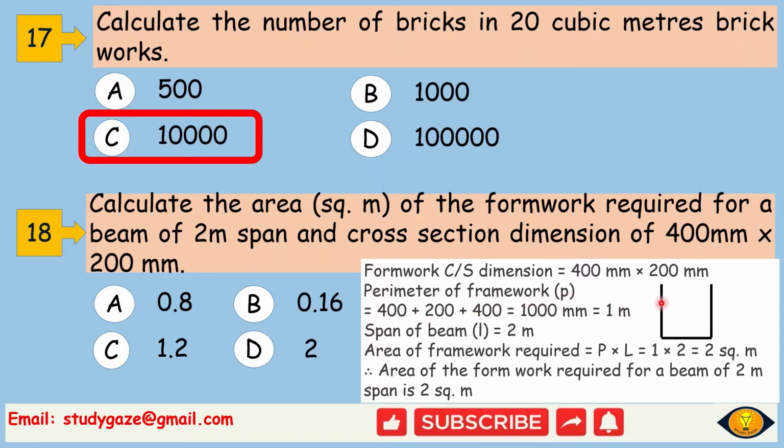Perimeter of formwork is 400 plus 200 plus 400, it will be 1000 mm, or you can say 1 meter, and the span of the beam is 2 meter. Area of formwork required is P into L, that is 1 into 2 equal to 2 meter square. The answer will be D, that is 2 meter square.